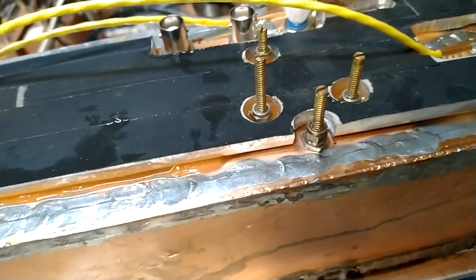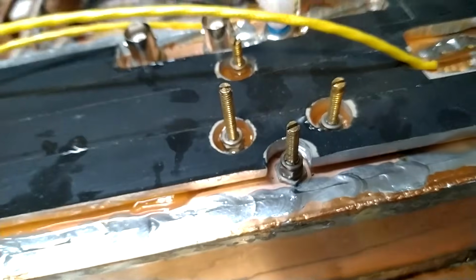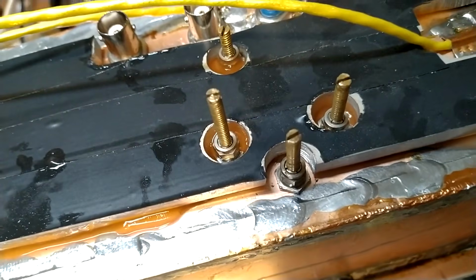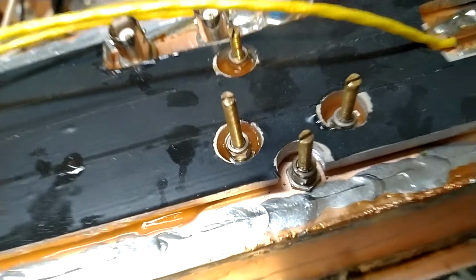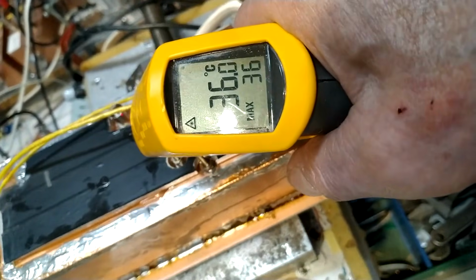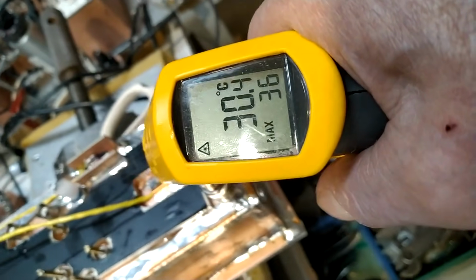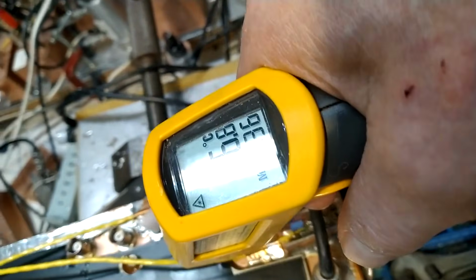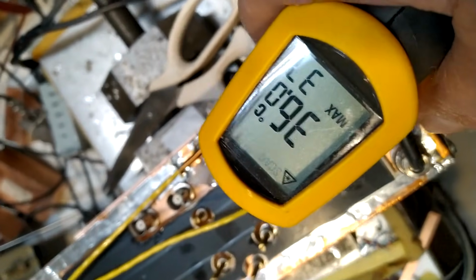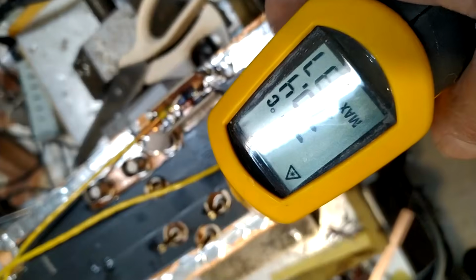I have placed 5 millimeters of aluminium on top of the box and put black tape on top of it to ensure a good emissivity of infrared radiation. I can look at the temperature. You can see 36 degrees. It's the same, almost. Oh, I have to point to the black tape. Otherwise, I see the reflection on copper, which doesn't emit well.